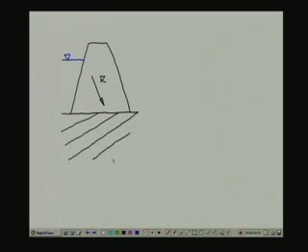and this is going to be the most favorable orientation because, as we know from our previous discussions as part of this course, the available shear strength of rock is going to be more if it is subjected to deformation perpendicular to the bedding planes than in the direction parallel to the beddings. So the strength of the rock that can be mobilized in this particular case is going to be maximum.